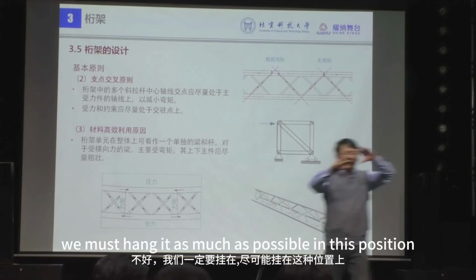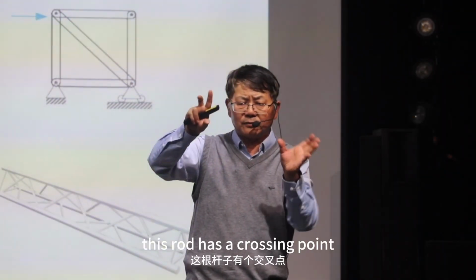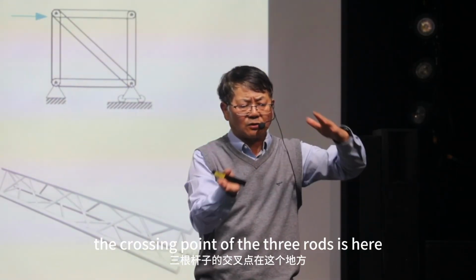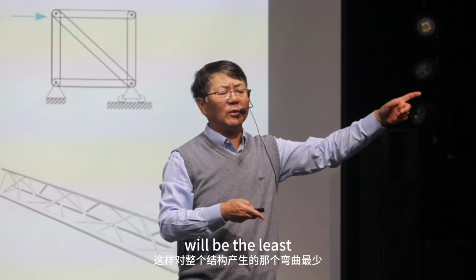No, we must hang it as much as possible in this position. Take a look. This rod has a crossing point. Can you see it? The crossing point of the three rods is here. We should try to hang the load at that point. This way, the bending produced in the whole structure will be the least.